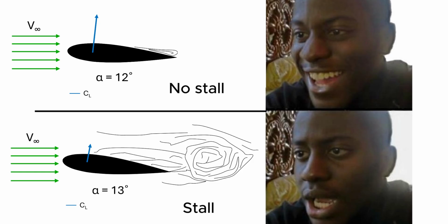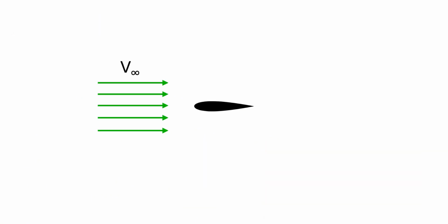For regular airfoil stall, we are always concerned with steady flows and a steady airfoil. When the angle of attack shifts such that it now exceeds the stall angle, the flow becomes detached from the airfoil, and the airfoil immediately experiences stall and the lift magnitude plunges drastically. But for dynamic stall, the fundamental difference is that the airfoil or the inflow itself is unsteady.